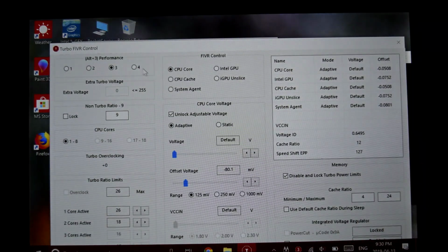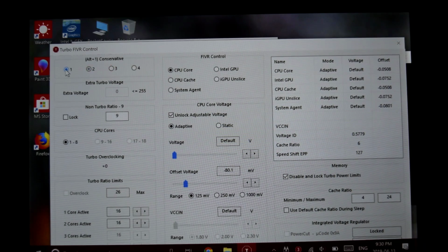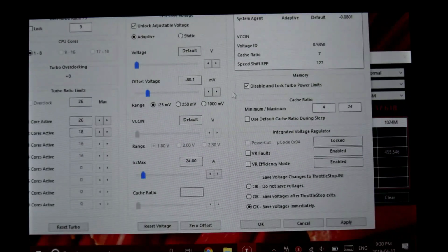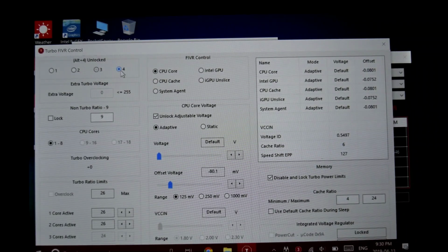So whatever you find, all of the undervolts will have the same number. Don't try and make different undervolts for different profiles. I did that at first. It's useless. You're gonna just crash your own computer by doing that, because once you go low, you cannot go back up. You have to restart the computer, remember that. So once you find your undervolts, you're gonna have a lot more power to play with at the same wattages as I showed you there.